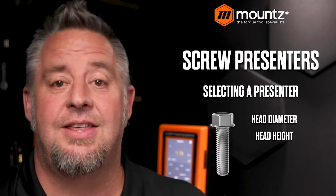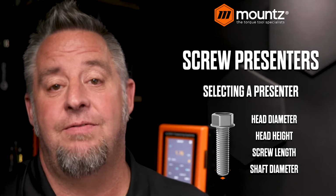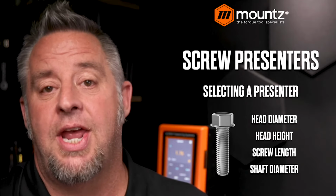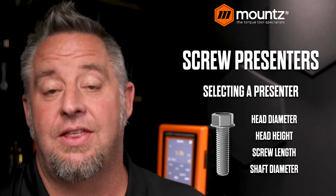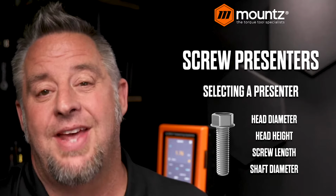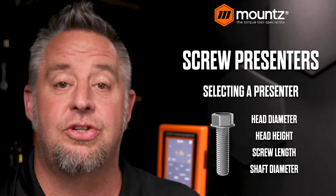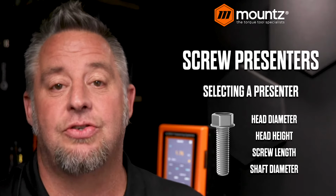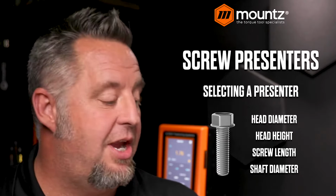Next would be the head height, and then also the screw length that we would be dealing with, and then finally the shaft diameter. Now there is one concern: the fastener itself must have a shaft, a screw length, that is longer than the head is wide. That is so that when the fastener is being processed through the feeder, it can orientate correctly and have that extra length to be able to fall into the rail system. And I'll show you what that looks like here in just a second.